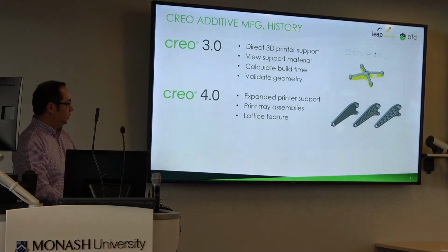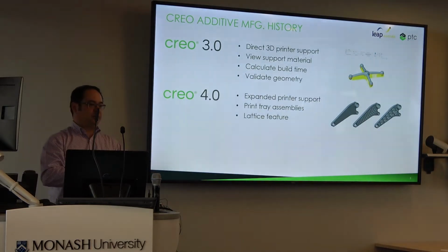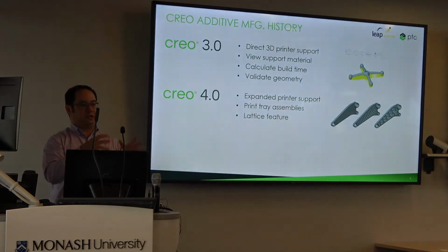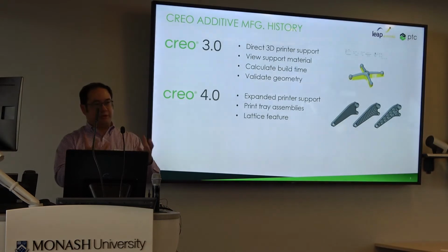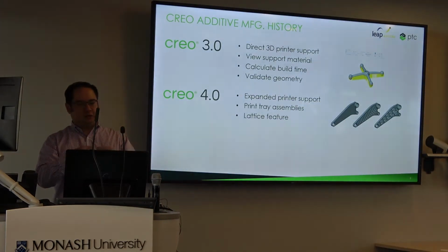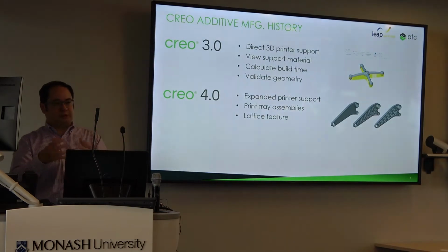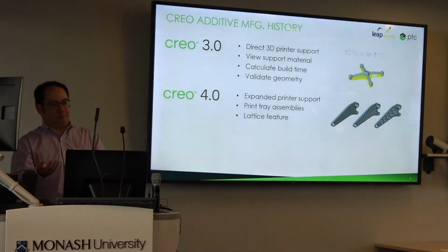Okay. So who has got 3D prototypes printed here? Okay. Who's 3D printing production parts that actually go onto the finished product? Only a couple. Okay. So typically, when you're printing a prototype, you're looking out for size and things like that. A lot of the software that comes with the printer has the options to hollow it out and fill that in with some sort of lattice structure inside it, to speed up the print time, with less material being used.